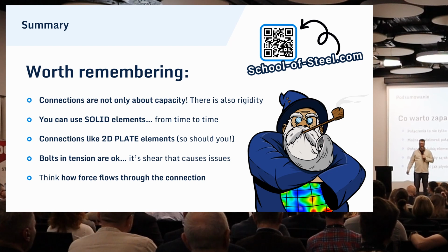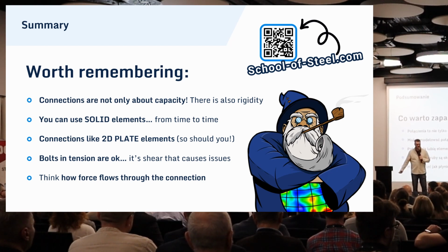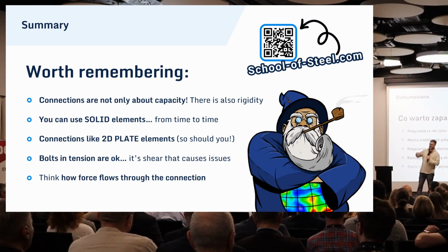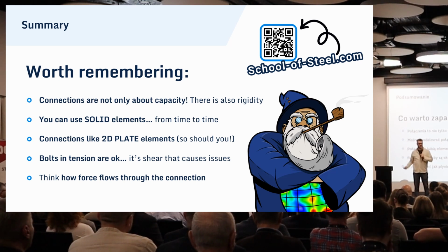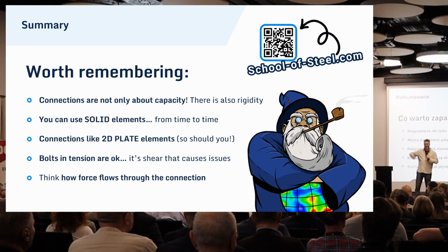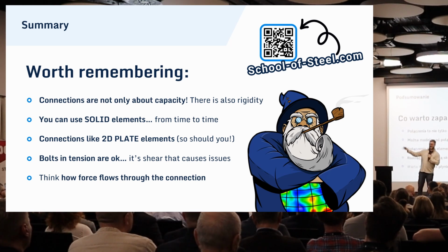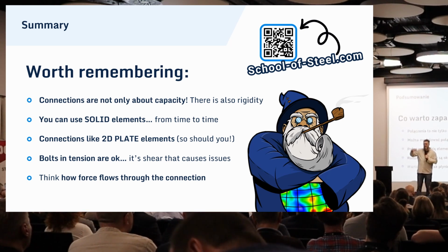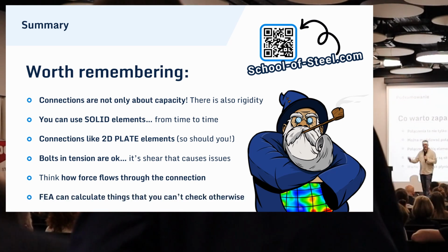Also, it's a good habit to think how the force flows through the connection. And even if you don't have the experience to kind of feel it, FEA is nice because it shows you all those maps that simply show you where the stress flows through your structure, and that is a huge benefit. So using FEA can help you to gain certain insight and experience when it comes to flow of forces through structures. And this is something that really will help you in your engineering career.